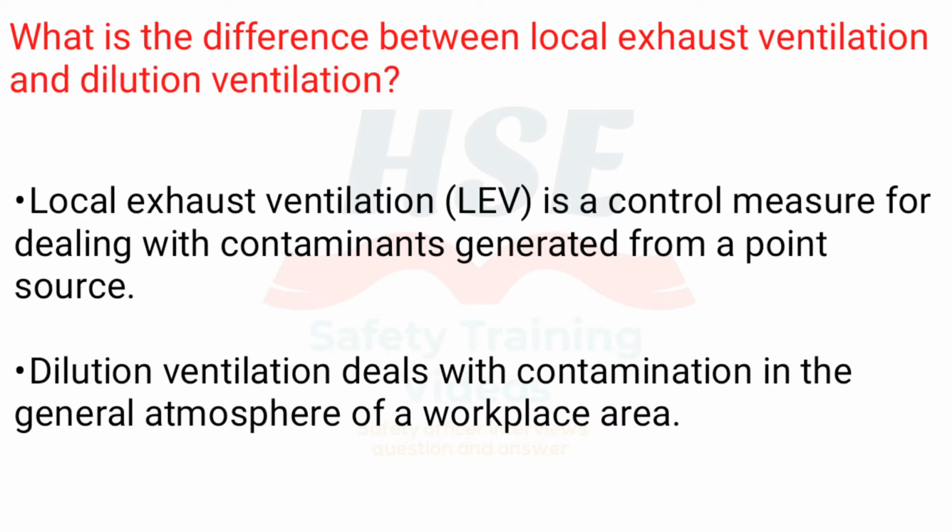What is the difference between local exhaust ventilation and dilution ventilation? Local exhaust ventilation, LEV, is a control measure for dealing with contaminants generated from a point source. Dilution ventilation deals with contamination in the general atmosphere of a workplace area.